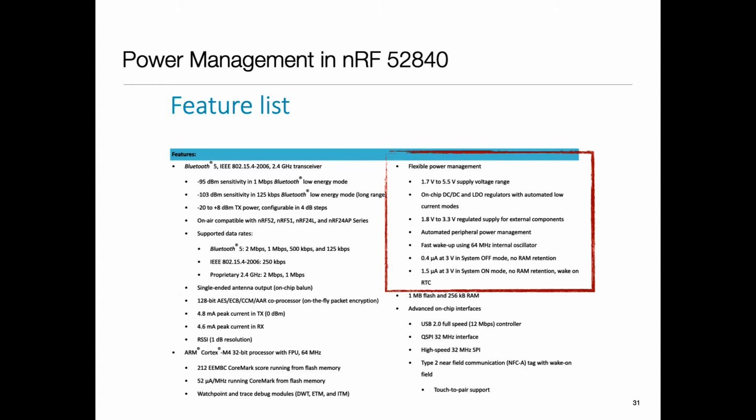It will describe what kind of features some of these processors have. Firstly, shutting the processor down is very common. There are many modes of shutdown. One is everything fully on versus peripherals shut down, everything else fully on, versus maybe memory is also brought down. So there are different degrees of shutdown.